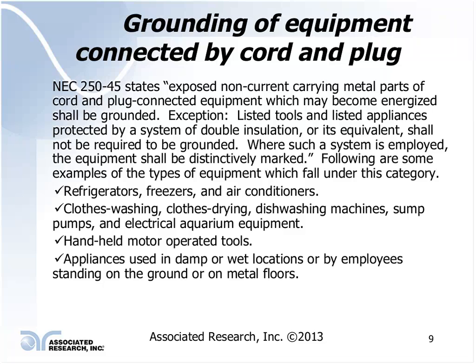So what they're requiring is 2 levels of protection should the basic insulation of the product actually fail. And so there is a backup to guard against any electrical shock hazards. One thing that is kind of common is that many of these products are used in a wet type application or could have water involved, or have pretty good direct contact with the individual using the product, such as handheld motor-operated tools.